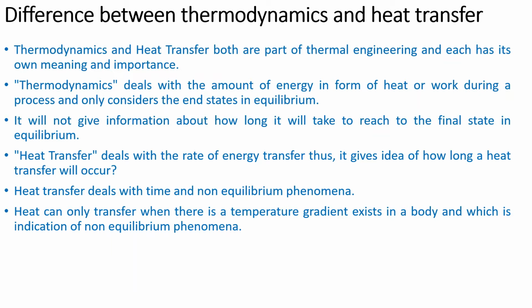Thermodynamics gives no information about how long it will take to reach the final state in equilibrium, while heat transfer deals with the rate of energy transfer. Thus, it gives the idea of how long a heat transfer will occur. Heat transfer tells us how much heat transfers and how long it will take to reach the equilibrium state.